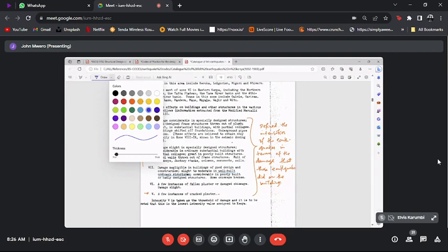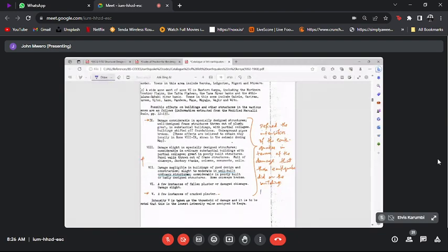So what the newer standards have done is that they have now defined the intensities of earthquakes by using the peak ground acceleration that the earthquake causes. So more recent standards use the peak ground acceleration. So how fast does the ground accelerate? And that's a more precise measure to use of an earthquake. So this is one place that is important to note.